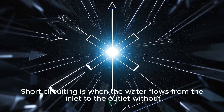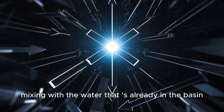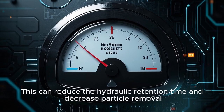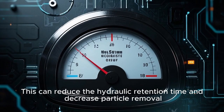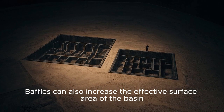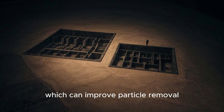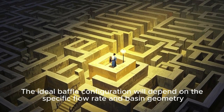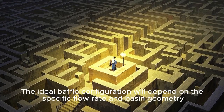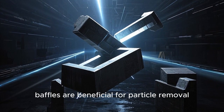Short-circuiting is when the water flows from the inlet to the outlet without mixing with the water that is already in the basin. This can reduce the hydraulic retention time and decrease particle removal. Baffles can also increase the effective surface area of the basin, which can improve particle removal. The ideal baffle configuration will depend on the specific flow rate and basin geometry. However, in general, baffles are beneficial for particle removal.